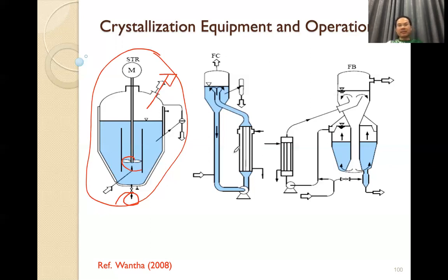another crystallizer, we feed at this point, and also the solution or mother liquor is mixed downward with the feed, and the recycled solution is sent to the heat exchanger, this is the outside heat exchanger, to heat up or cool. In this case, we use the exchanger to heat or cool to generate the supersaturation. It may be by cooling crystallization or by evaporation crystallization.